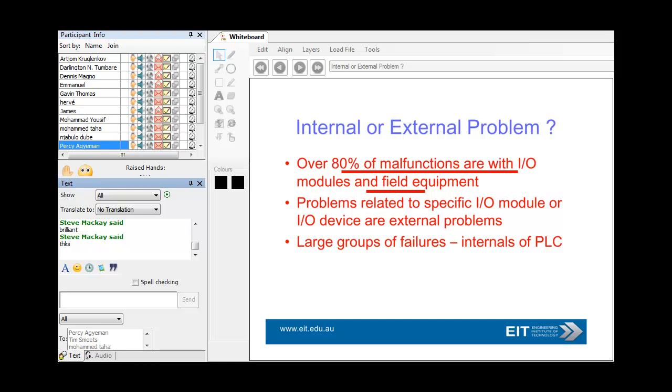So you can assume that most of the time your problems with the PLC relate to something outside the PLC. Everyone instinctively looks at the PLC as a black box and immediately thinks there must be something wrong with the PLC, especially a guy who hasn't worked with the PLC. That's one of the major problems, I think. Whenever you set up a PLC system, you have to make sure your program works smoothly and the system has predictable problems, or you can identify them very quickly. There's nothing that drives a client into a catatonic state more than not knowing what the hell is going on with this PLC system as far as controlling the plant and all the problems it has.